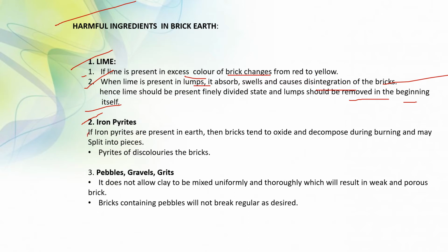Number 2, iron pyrites. If pyrites are present in earth, then bricks tend to oxidize, decompose during burning and may split into pieces. Pyrites also discolor the brick.